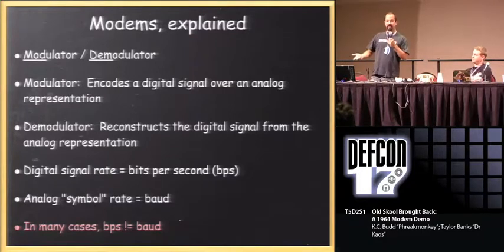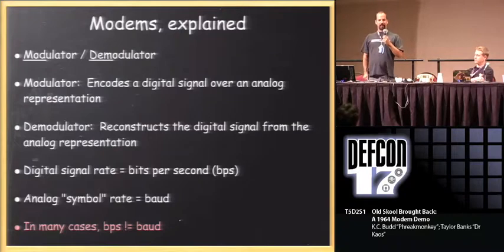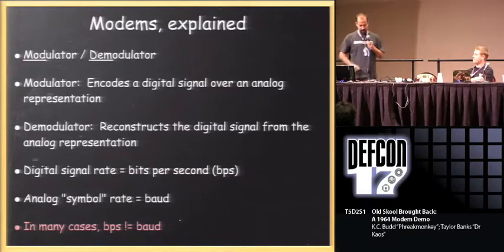They then improved the modulation, and what everybody calls a 2400 baud modem is also actually 600 baud. So we've been calling modems by the wrong thing ever since the 300 baud standard went to 1200 baud. Just worth mentioning because I'm going to get into how the modulation works in a minute.